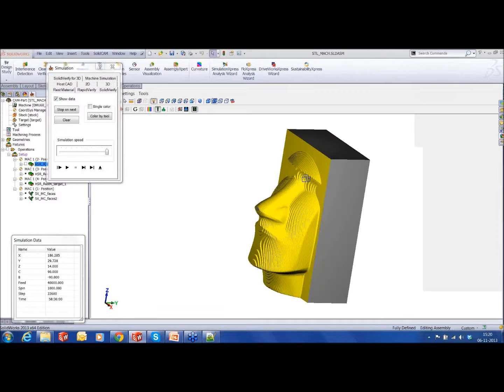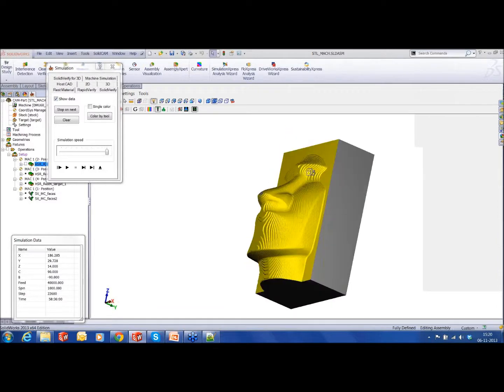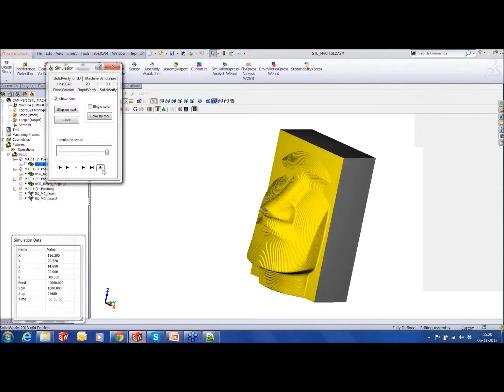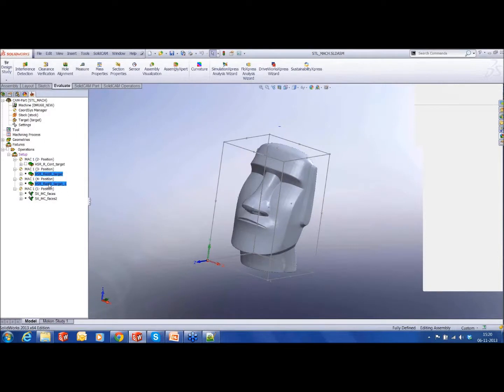So from the first setting, this is what is achieved. Right, let's calculate the other two toolpaths, which are nothing but rest roughing toolpaths for HSM. And then we will jump into the 5-axis calculations for this particular part. And I'll show you the underlying principle on how we do the calculations for 5-axis.